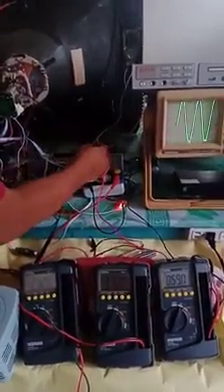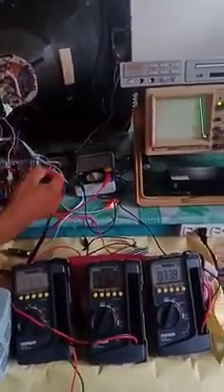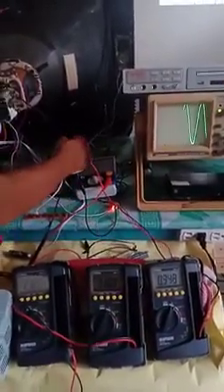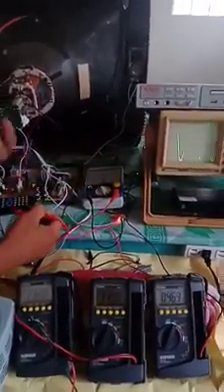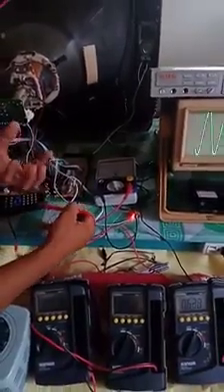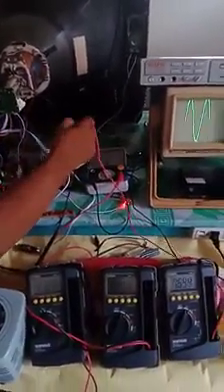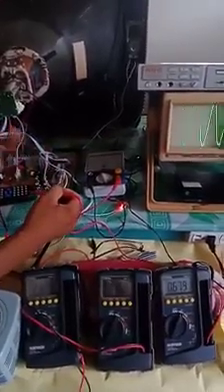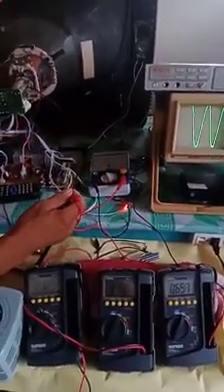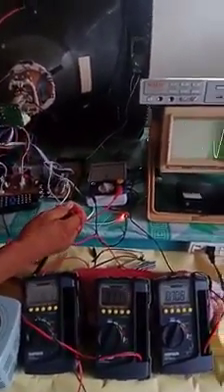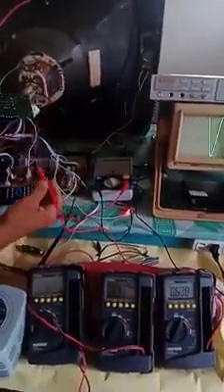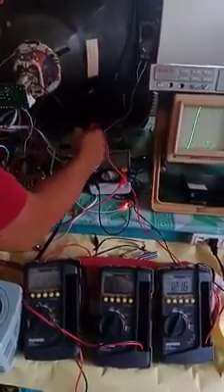Like for example, this EEPROM is a digital IC. This UOC, or Unified One Chip, is a combination of Jungle and MPU. MPU, by the way, is microprocessor unit or microcomputer unit that uses digital circuits. It is combined with analog, because the Jungle circuit, comprising the color killer, chroma amplifier, sound IF amplifier, and luminance amplifier, uses analog components. So, a combination of analog and digital.